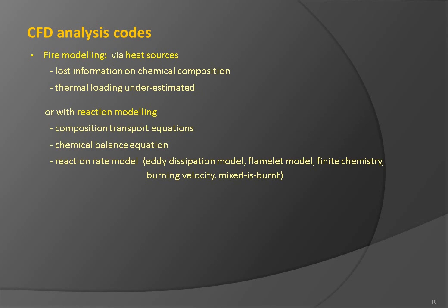Different reaction models, such as the eddy dissipation model, flamelet model, finite chemistry model, burning velocity, or mixed-is-burnt model, to name just a few, correspond to specific chemical and flow conditions. A CFD practitioner should understand their applicability and especially their limitations.